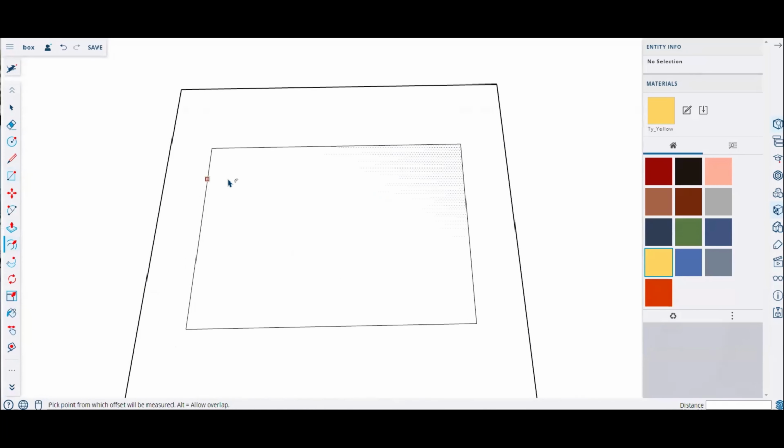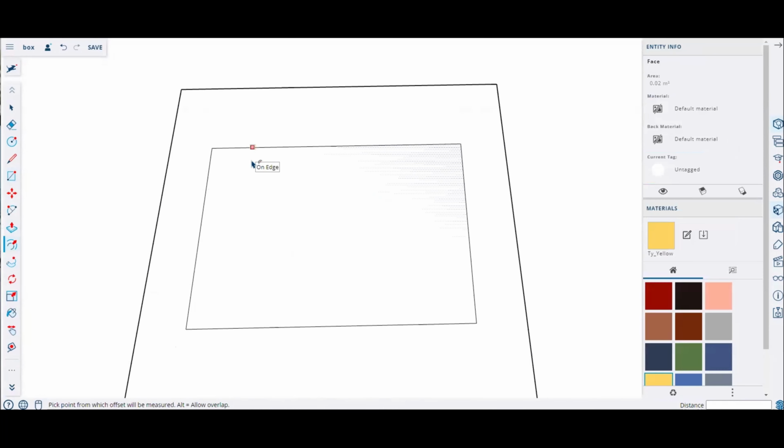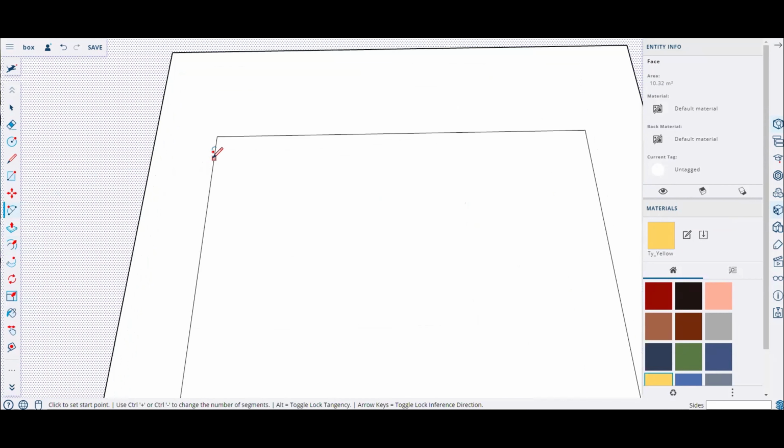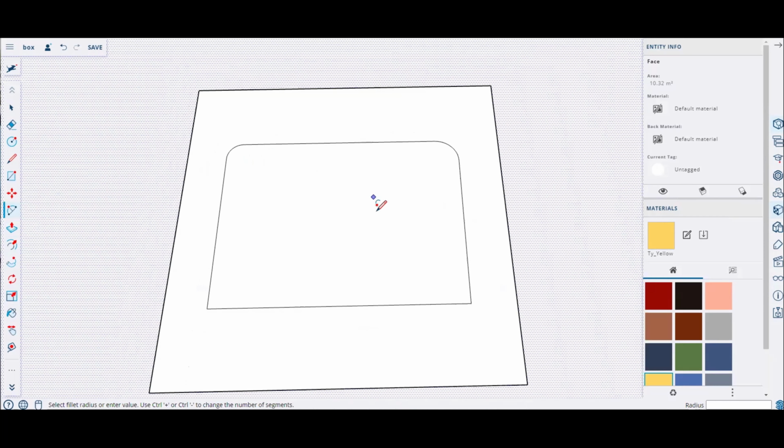drawing the radiuses now, the fillets now, because remember, we're drawing in 2D. This software doesn't have a fillet tool, sorry. So you have to create it yourself. So in this case, you can go like this. And see when I click onto this, only when it turns pink will it delete the other lines. See, I didn't delete it now? Right, so it's not a perfect circle. And now I'll delete it. Now, if it doesn't delete, you can just go along and use the rubber and delete it.